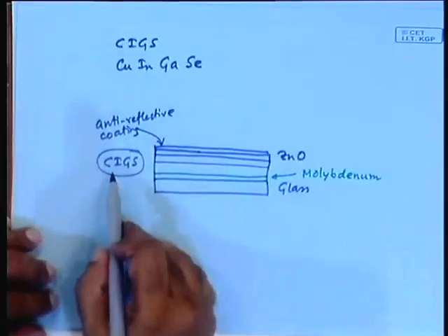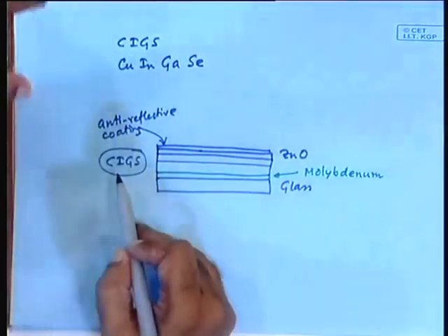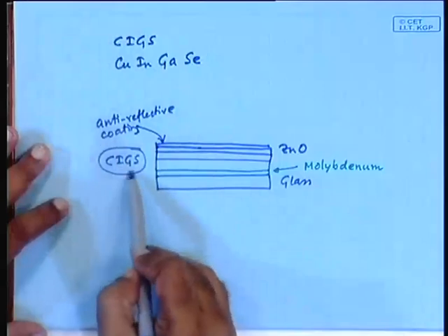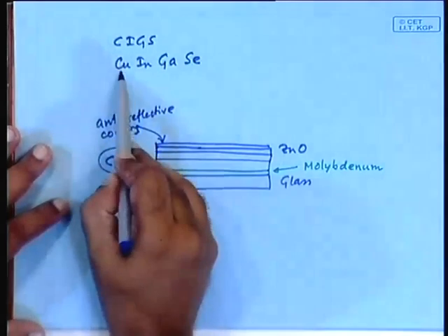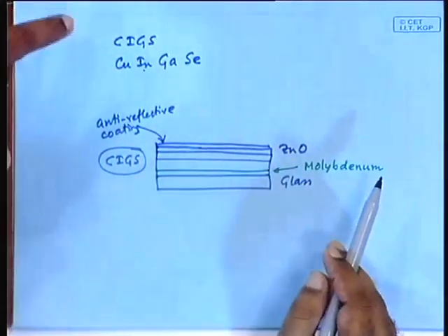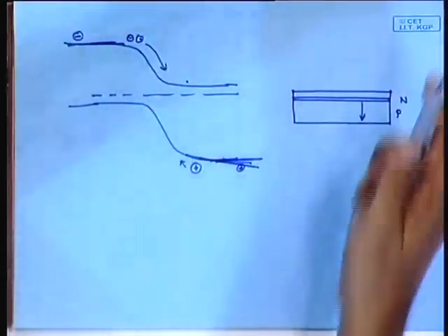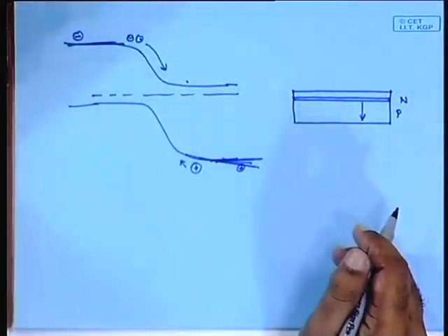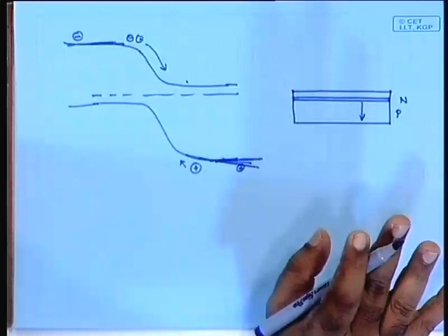For example, when I was talking about the CIGS deposition, the concentration of the individual components is varied as it is deposited, and as a result you automatically produce a graded band gap. So, you have this technology inbuilt in all the different types of production technology that we have talked about.